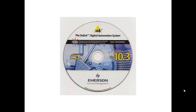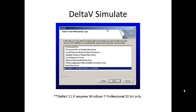Take the default install path as you install DeltaV. The critical selection for DeltaV Simulate is on this dialog. Select Simulate for standalone workstation or laptop, which will install a standalone version of DeltaV with DeltaV Operate.